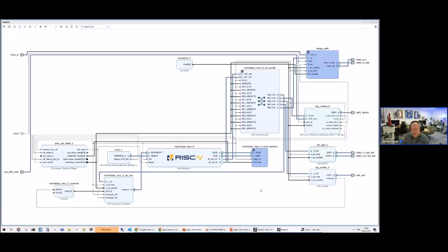So we've got a relatively small, it looks large on the diagram, a relatively small microprocessor controlling the system. I've got a UART for reporting, and then I've got a GPIO. The role of the GPIO is to drive the hot plug detect on the HDMI camera. That's its entire role. It's going to be software controlled. As the software's gone through and it's ready to start receiving the image, it's going to drive the hot plug detect such that the camera starts outputting its data via the HDMI and not via the screen on the back of the camera.